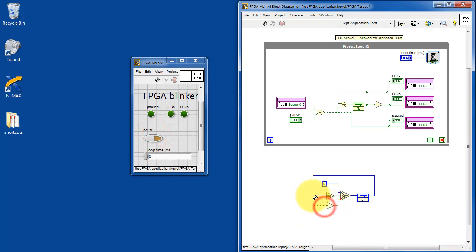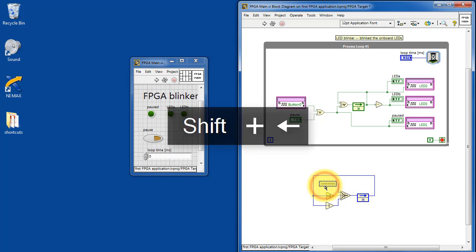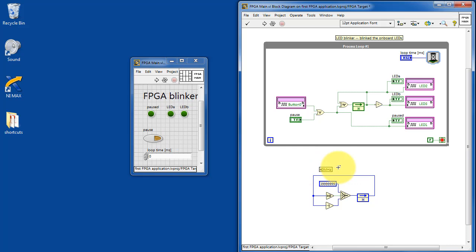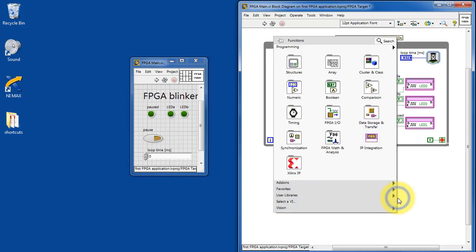But if it has not yet reached 0, then we decrement the count value. We have a 40 megahertz clock. That's 40 million cycles per second. So we'll load or reinitialize the counter to 1 less than 40 million. Therefore, the counter passes through 0 exactly once per second.